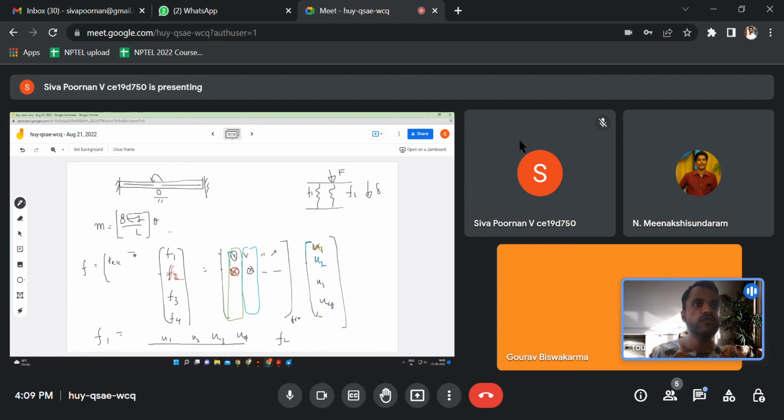You're able to do that because first you are always able to write this as known u and unknown u, and the known u are going to be zeros. Okay, mostly, not necessarily always zero. You can have cases where they are finite and non-zero, but still you know them. That's what the idea is. You know these u values and you don't know these u values. And how many rows are appearing here? Same number of rows and same number of columns.